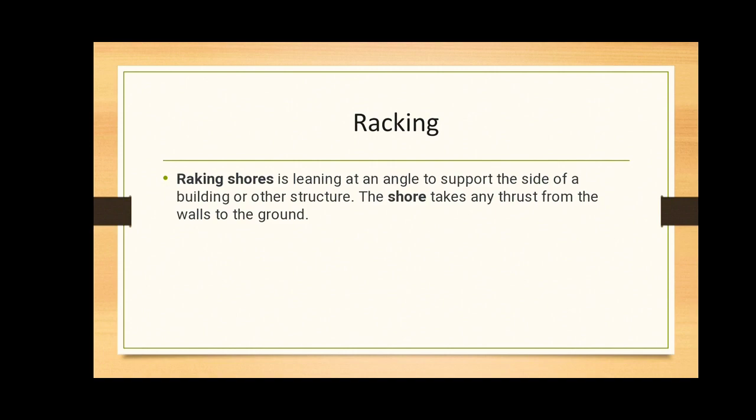For greater heights, additional supports are given at lower elevation for more restraint. Breast timber shoring is used when heavier loads are to be supported, and for walls which are likely to bulge or crack, vertical timber plates and a series of two or more shores may be required in such cases.